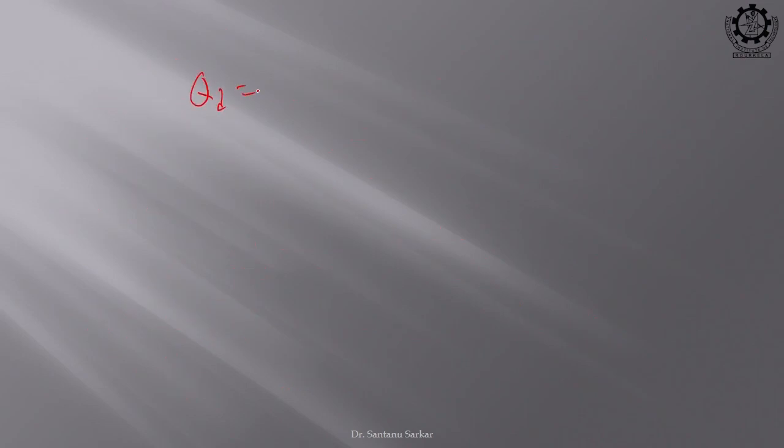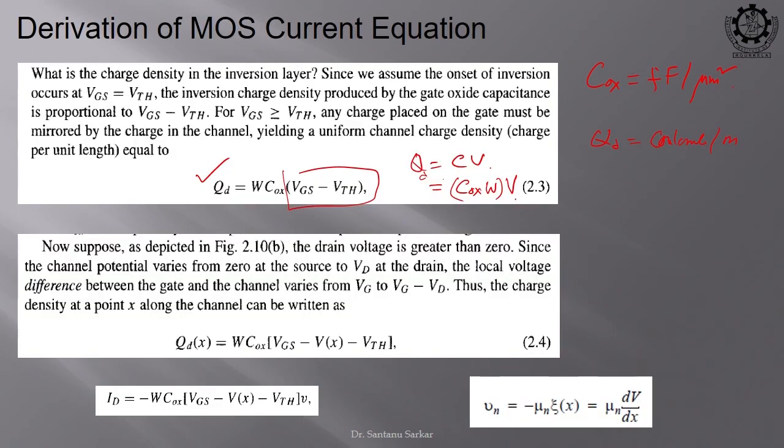So, our QD is equal to COX into W into VGS minus VTH minus V at position X. That V at position X is coming due to the portion of the drain potential, the effect of the drain potential. So, this is our total QD. Now, what is I? I is equal to this Q into V. And what is our V? This velocity is mu n into field.